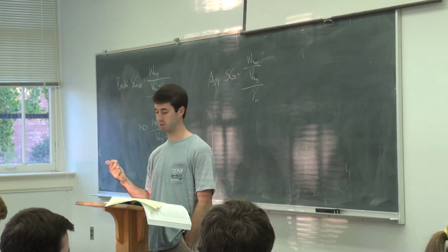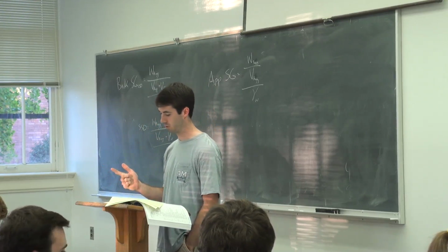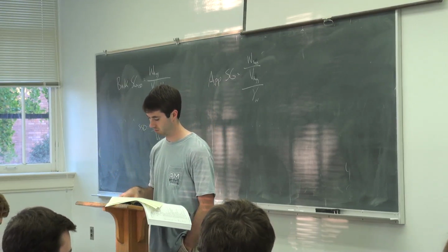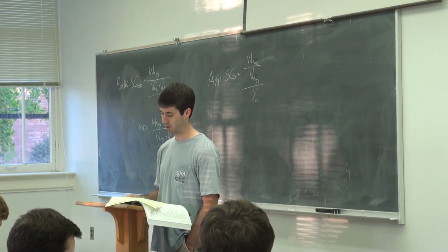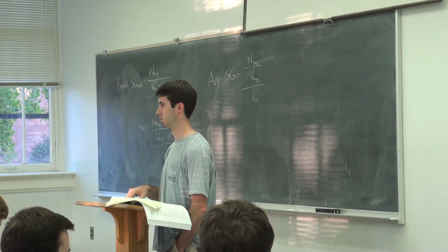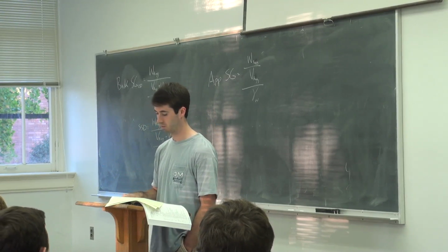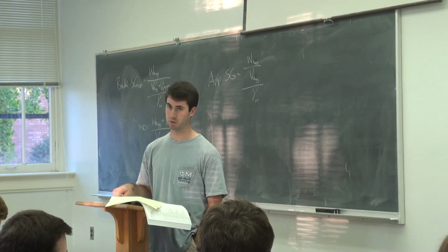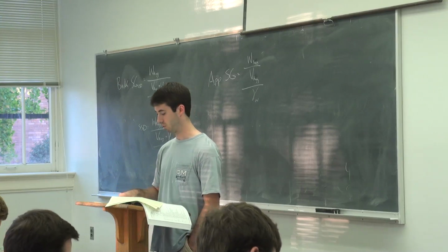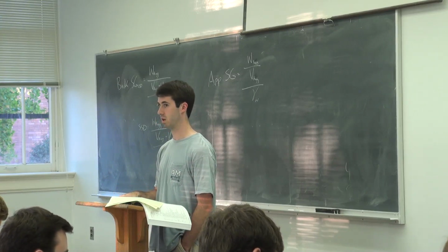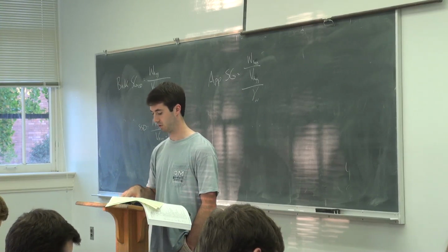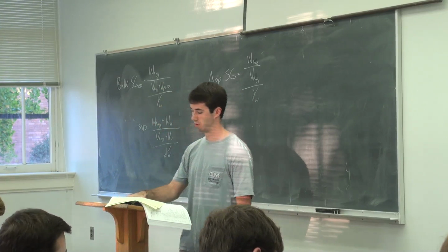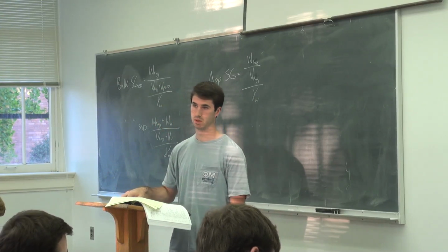You want a certain strength, workability, durability, and economy. For strength, you got 4,000 psi. For workability, 3 to 4 inches of slump. For durability, 6% air. And for economy, 1 inch max coarse aggregate.